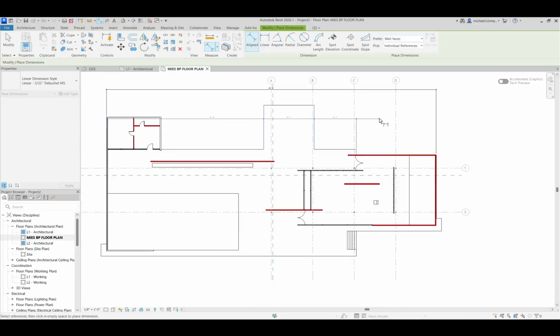But because I don't want to close dimensions because I'm rounding up, it might create an error between real and rounded math. And I don't want a contractor calling me and saying, well, this dimension says this and that dimension says that. Which one's accurate, right? So in order to solve that, I just leave one dimension open-ended, and then I don't have to worry about the contractor bugging me with that.